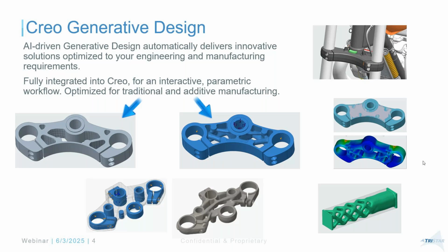That's the traditional optimization, where we were using specific dimensions and then using the software to crunch its numbers when we change those dimensions. This is slightly different, wherein we are giving it a volume and having it say, okay, I want to reduce the volume by 30% or 50% or 70%. I'm giving a goal as a percentage of the original volume, and then having the software give me some geometry depending on the constraints that I've applied here, right?